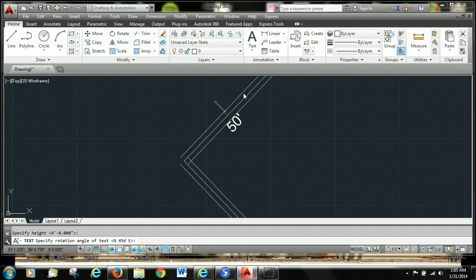And then I'm going to type my bearing. In this case, north 45. And you can either do D for degrees, or you can type percent, percent D, which does the degree symbol. It's a shortcut in dtext only.